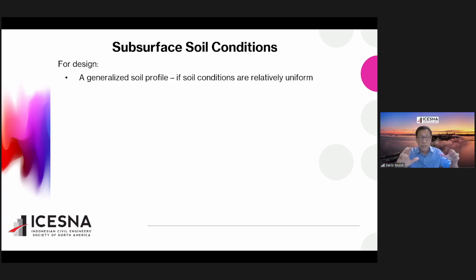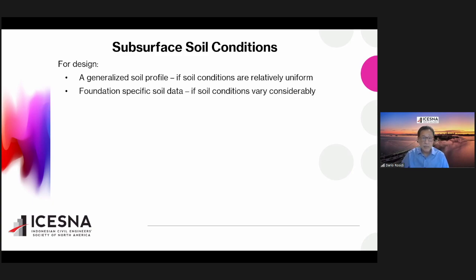Foundation, right? So it will be faster to do the design because you only use one profile. But that's only good if your soil condition is relatively uniform. But if your soil condition varies considerably across the project, then typically you cannot use a generalized soil profile. What you typically use is the foundation-specific soil data.